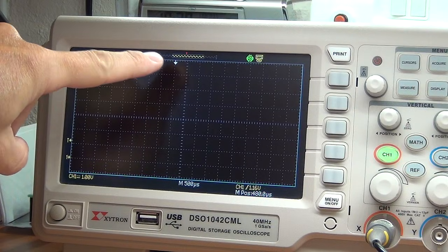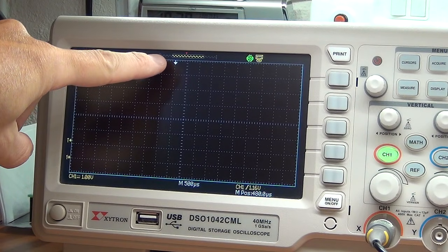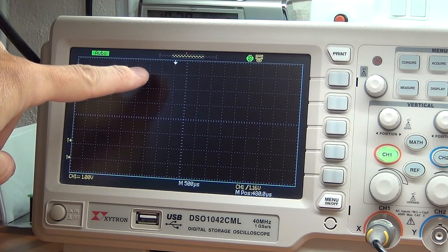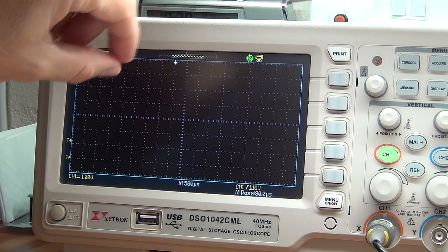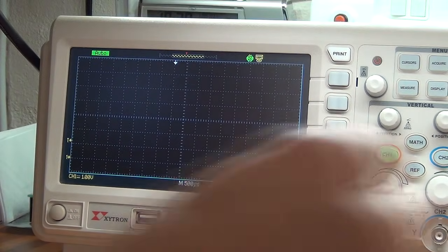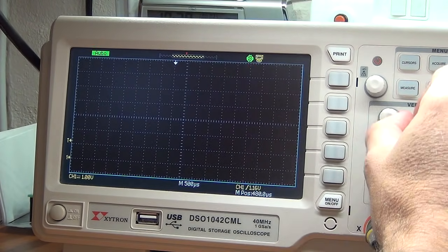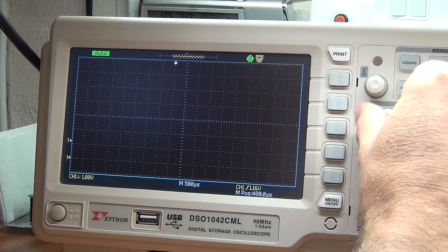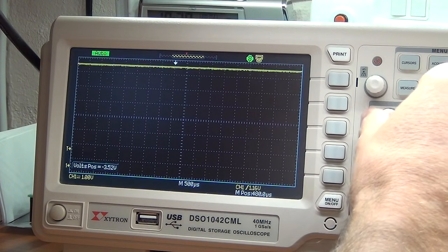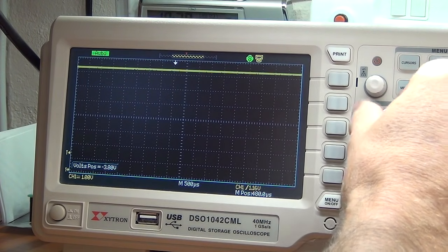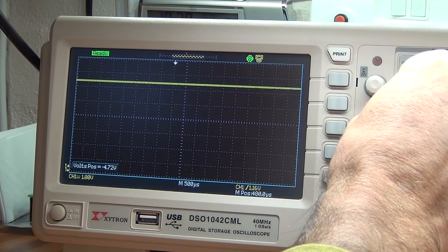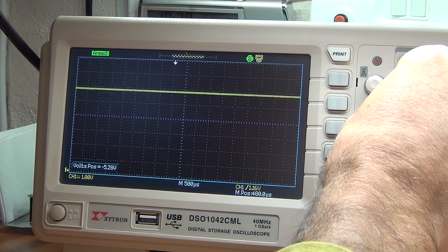And there's a little indication of that on my oscilloscope. You've got this little arrow which points that the signal might be sitting higher up. So this leads into two things: me showing you what that signal looks like, and then using the buttons or knobs to actually bring signals into view. What I'm doing now, I'm using the vertical position button, which we'll discuss now, to bring that signal down so that we can have a look at it.